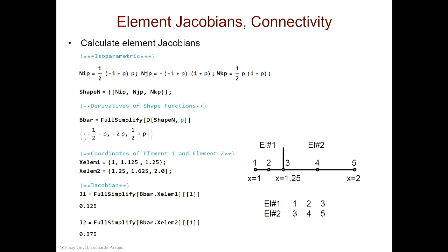All right. Shape functions are the same for every single element. Every single element has the same shape function. I put them in a matrix so I can take the derivative of this at once. So I get B bar. That's B bar, the derivative of this. By the way, since this is coded up in Mathematica, for the previous example, I could have just left it there. But just to remind you that this has to be calculated, okay?